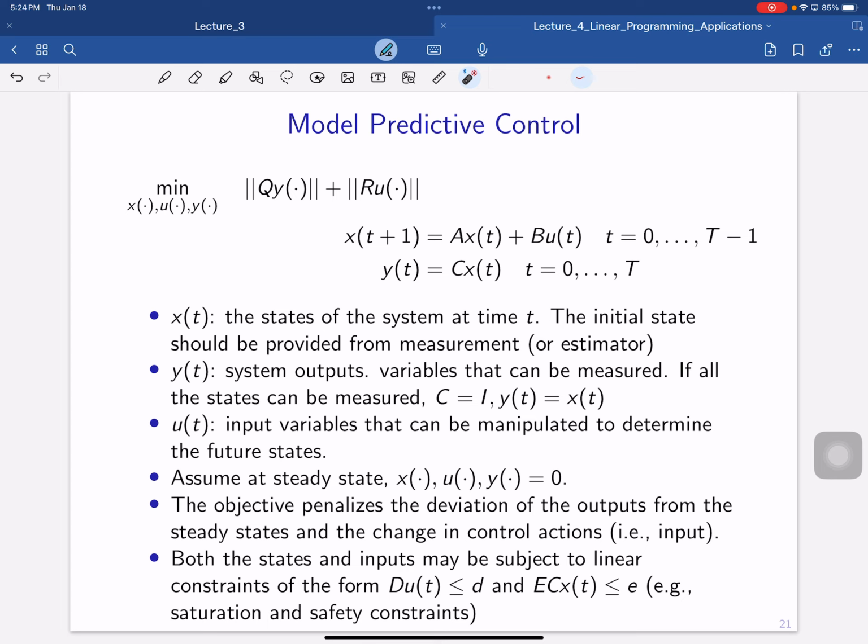And if you think about other applications, it's not just about controlling a CSTR, it can be control of anything. For example, if you want to control rockets, the state of the rockets could be the location and the angle of a rocket. Then the manipulated variable could be how much fuel or acceleration you want to give to the rocket, such that you can land at a given location. You can always use those types of model predictive control models.